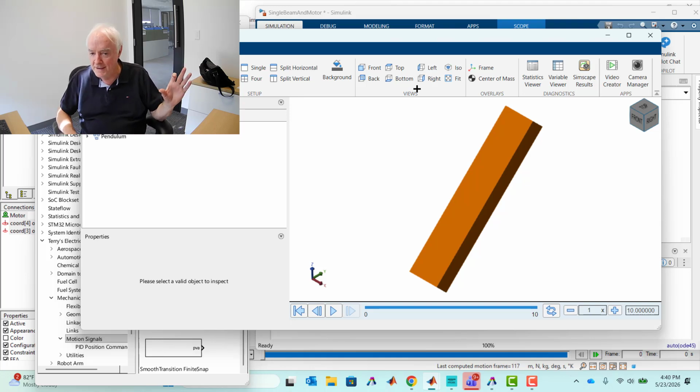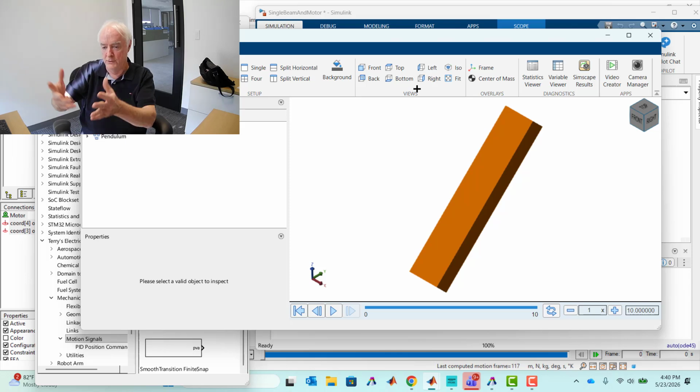So I can do this very inexpensively because I am using this inverse dynamics to supplement the controller and allow the PID to operate at a reasonable rate and do the thing it's really good at, which is attending to the stability of the system.